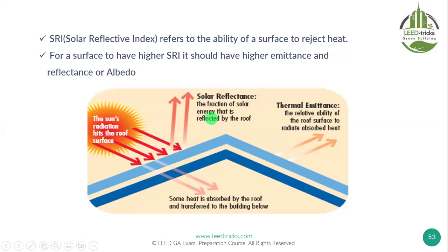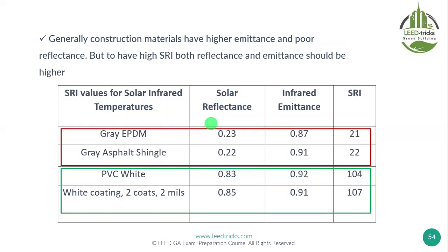In the market, material suppliers call it cool roof. Cool roof. So for solar reflectance, the higher is better, like what you see, white coating and so on. It goes from 0 to 1 as a fraction, or from 1 to 100. But gray and black are low. So they are not reflecting. Where does it go? Of course, it is absorbed.